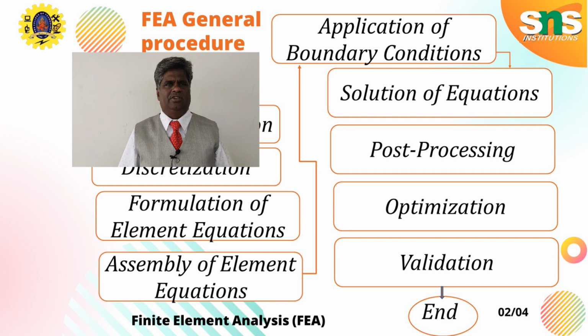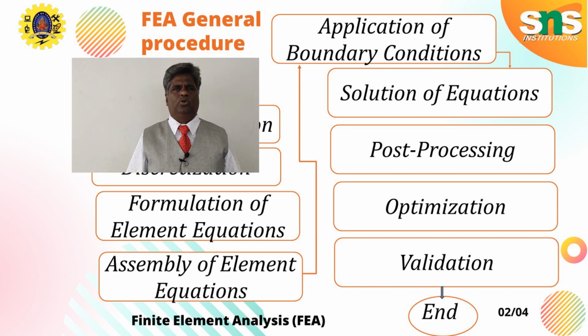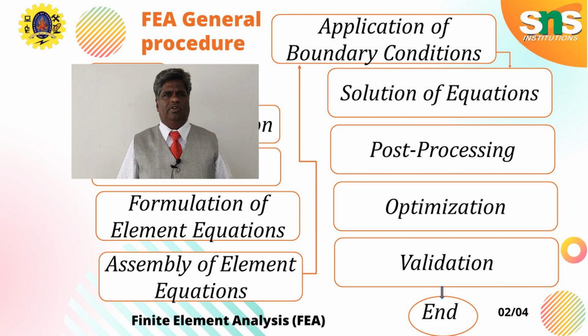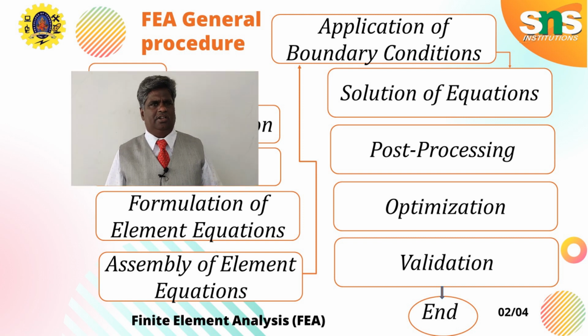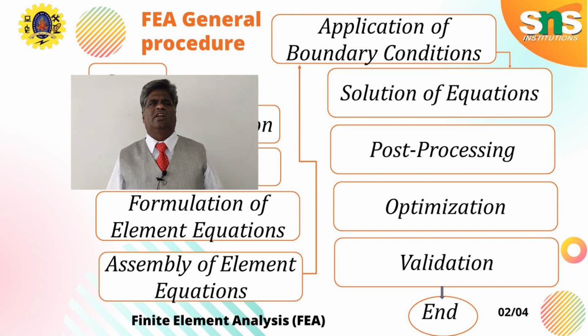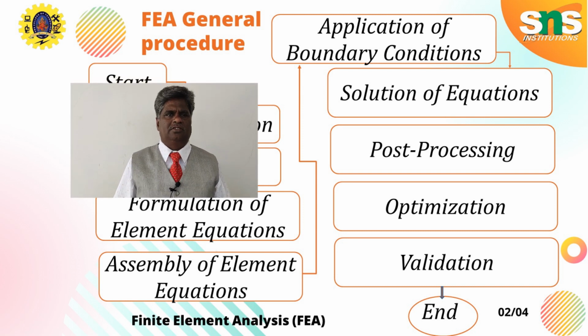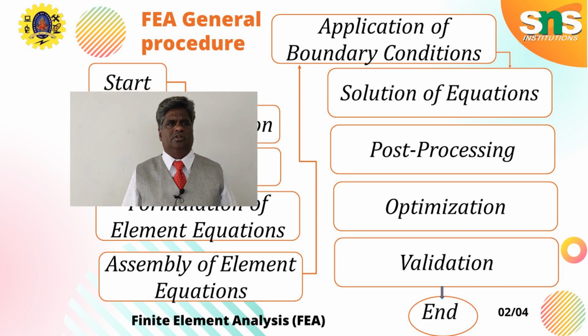Assembly of finite element equations: the element equations are assembled to form the global stiffness matrix and the load vector for the entire structure. Application of the boundary conditions: the boundary conditions are applied to the global stiffness matrix and load vector to obtain a reduced system of equations.